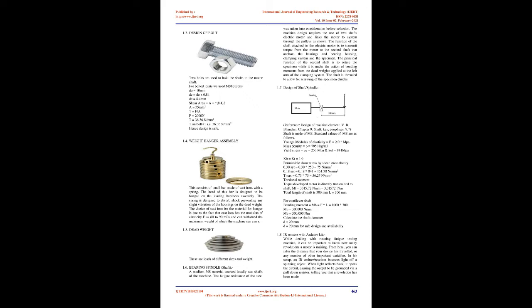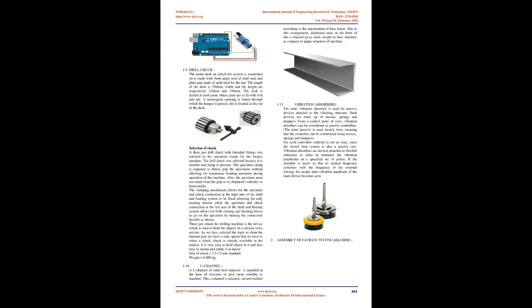The bearings selected for the design were self-sealed spherical roller bearings, which have high load carrying capacity and can accommodate misalignment and shaft deflections of a maximum of 0.5 degrees. Bearings of 22 mm bore diameter were selected for the design. It was ensured that the bearings would allow for the mounting of all components onto the shaft physically, and that the mass of all components including the bearings was minimized.